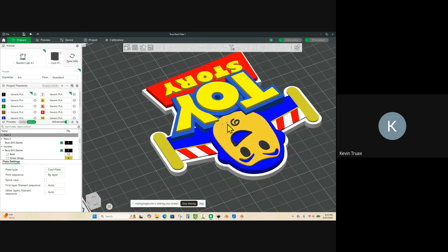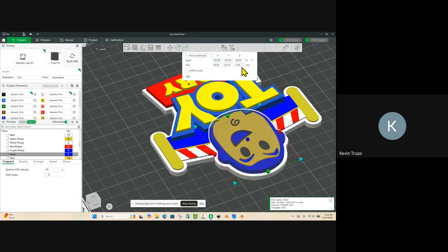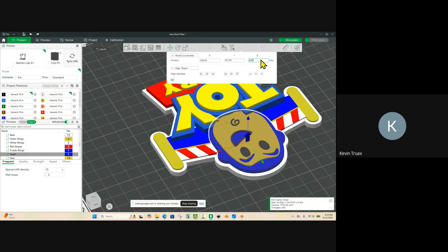So we have a step down right there, like we really need. So I'm going to go ahead and do that. I'm going to take our head here, and let's make it 3 instead of 4. That's going to change our Z height though. So half of 3 is 1.5. So our Z height should be 5.5.